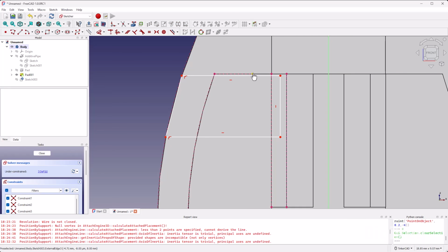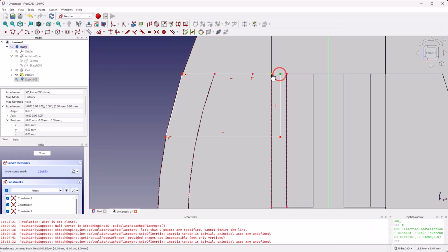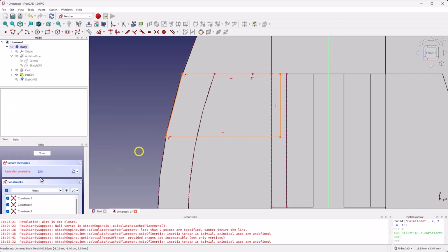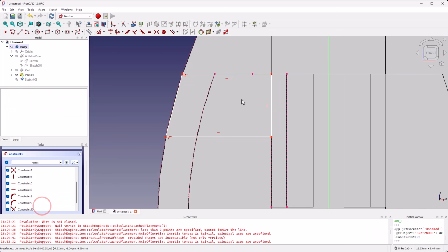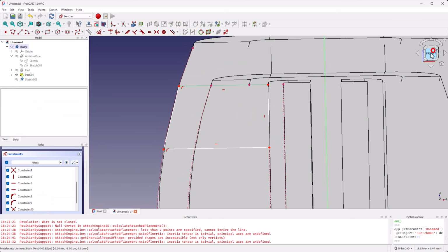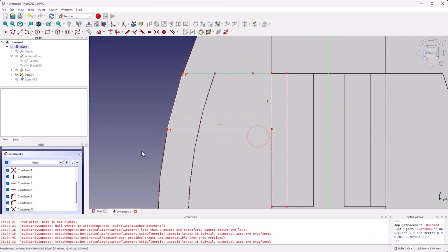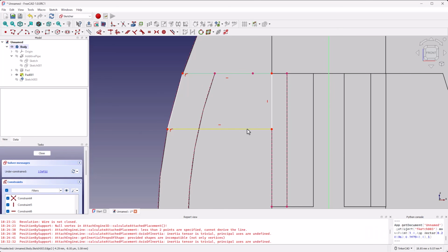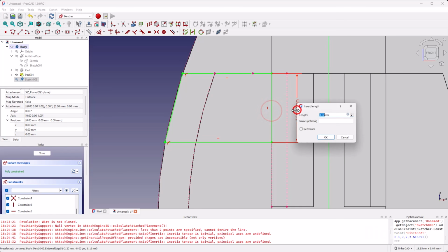And let's attach this line to this line using the coincident constraint tool. And we're going to attach this point to this point. There's a redundant constraint, which is number 10. Let's get rid of that. And now all we have is 1 degree of freedom, and that is the height of this. So dimension tool, let's bring this out. I'm going to make this 3.5 millimeters. At least for my testing, that should work with my keycap stems.